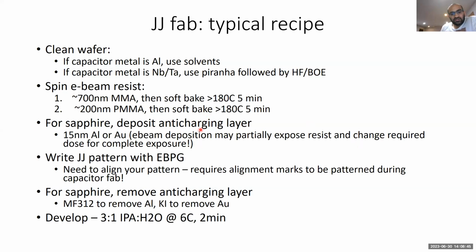And this basically is just telling you that depending on what you use for your anti-charging layer, and what thickness of anti-charging layer you use, can ultimately have an impact on the overall doses that you use for your junction patterning. If you're on silicon, because silicon is conducting at room temperature, you don't need to do an anti-charging layer. And then you just write your junction pattern